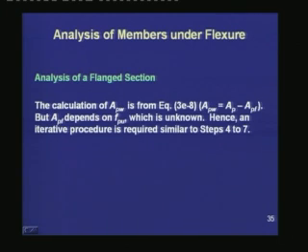Now, we had seen that as the pre-stressing steel increases, omega Pw will increase and the value of XU will go up. That means, with increasing amount of steel, we need larger depth of the compression to balance the tension in the steel, and also with increasing omega, beyond a certain value the stress in the steel decreases. That means a lower amount of stress in the steel will be able to equilibrate the compression in the concrete.